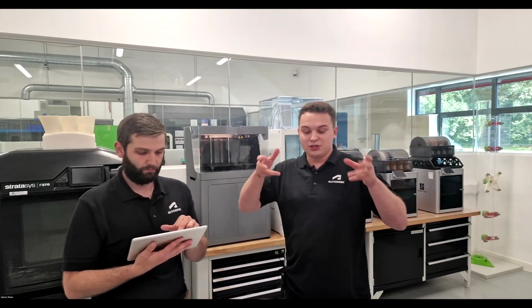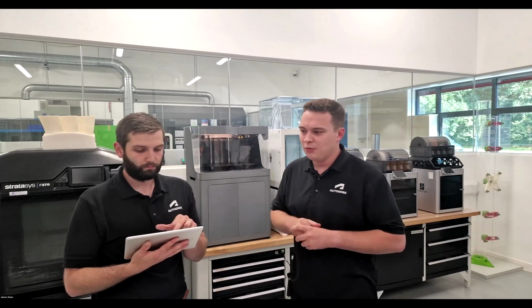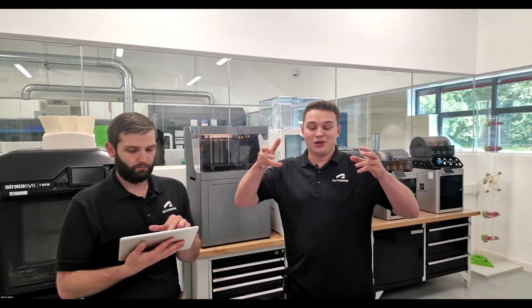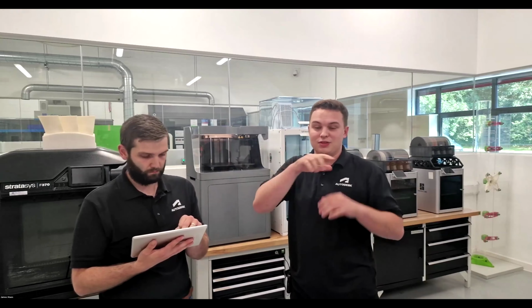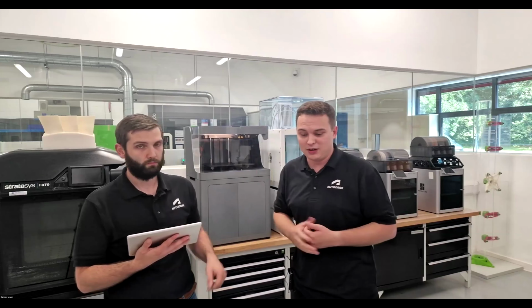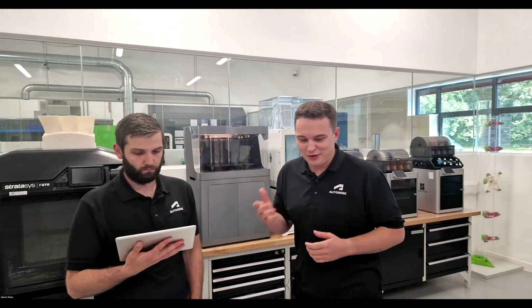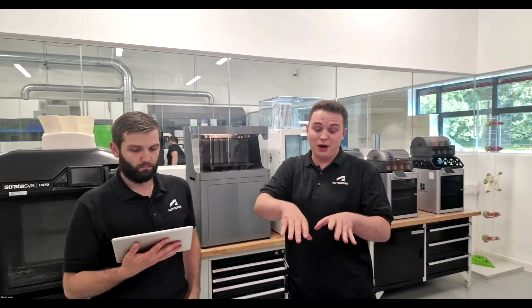Yes. So for this part specifically, the way the tool works is it actually is rotated. You may have noticed inside the tool, there was a precision number. I can put in 0.1, I think it must be a degree, 0.1 degree. And what it actually does is rotate that part through those dimensions and then project every single time. I believe that's how it works. I'm not a developer, but that's how it looks like it works. And as a result, for this part specifically, you get those broken lines.